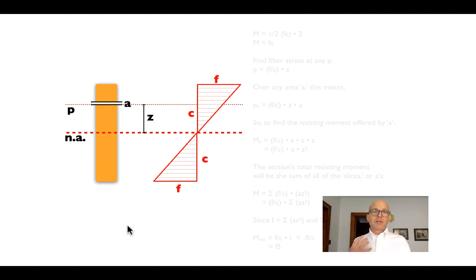So the cross-sectional strategy that we have, if you think about it: the longitudinal strategy is don't put material at the ends of the beam where you don't need quite as much resistance to bending moment. The cross-sectional strategy is don't put much material around the neutral axis. Do what you can to remove that lazy material around the centroid of the beam. So how do we do that? How do we take the lazy material out of a W shape?